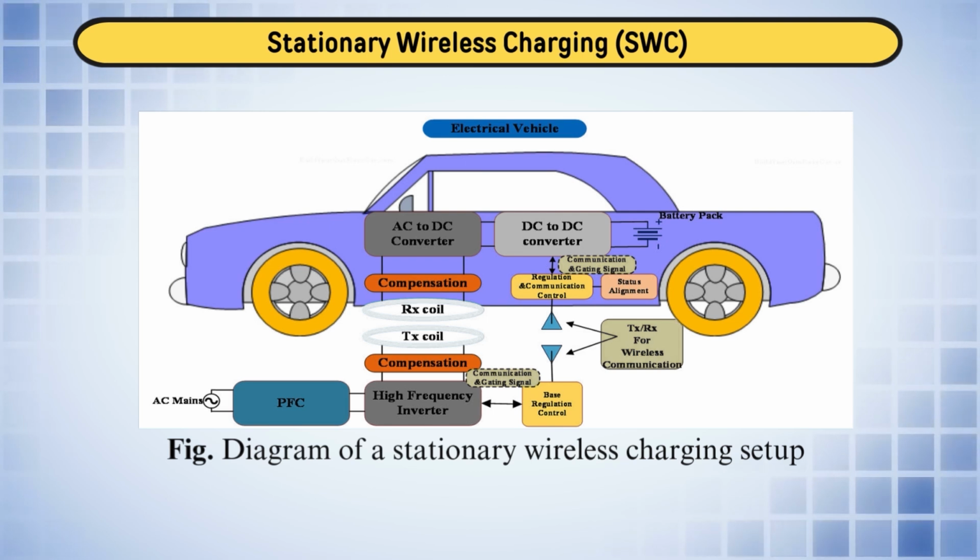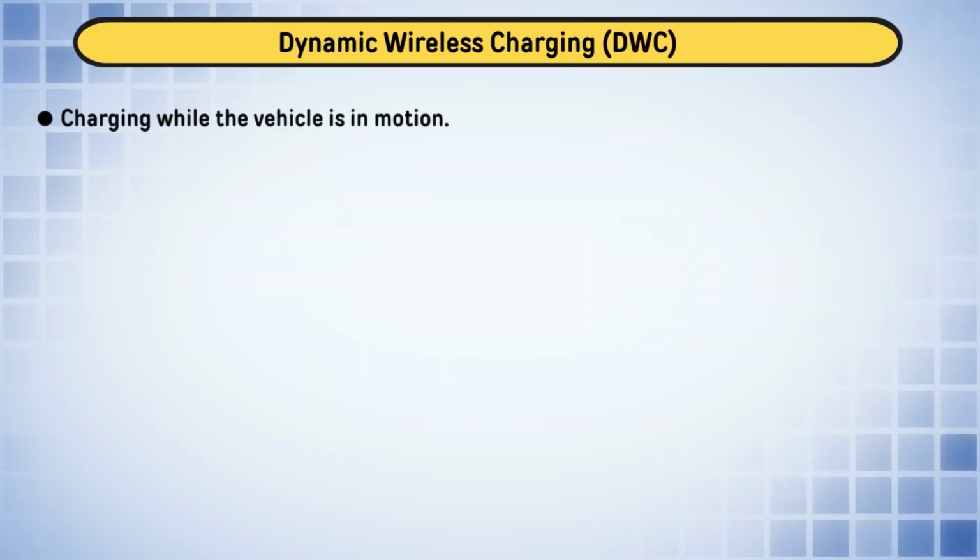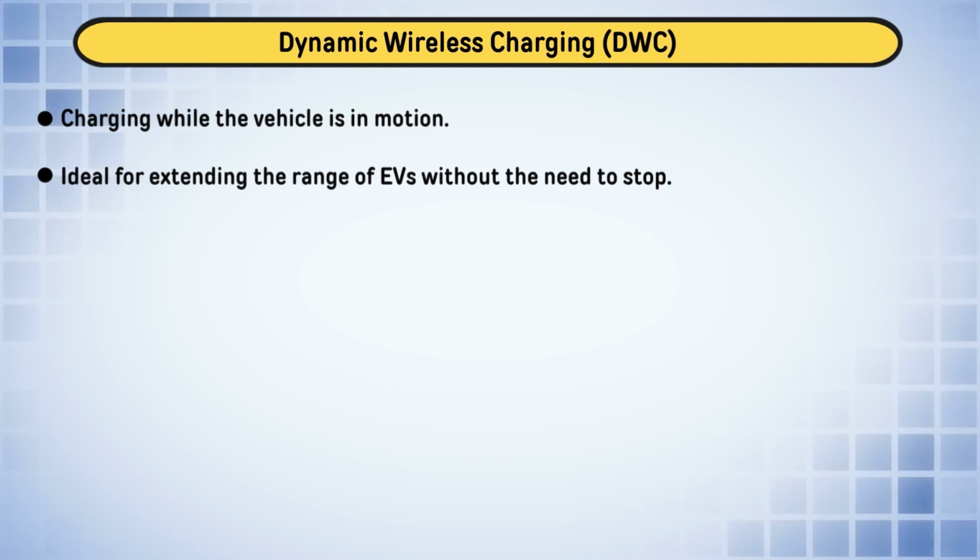First, we have seen the non-isolated basic standard topologies. Now, we will go for the isolated type of EV charger. Here we can have more converters under the isolated type, but here we have shown the basic three topologies. One is flyback, and the application of flyback is for low power. It is widely used in SMPS, switch mode power supply, computer power supply, laptop power supply. This flyback converter is very famous.